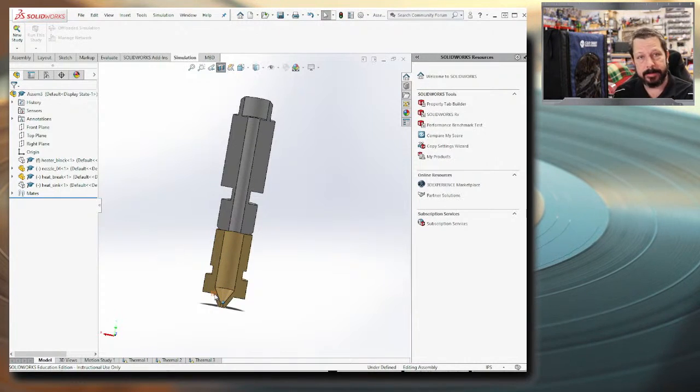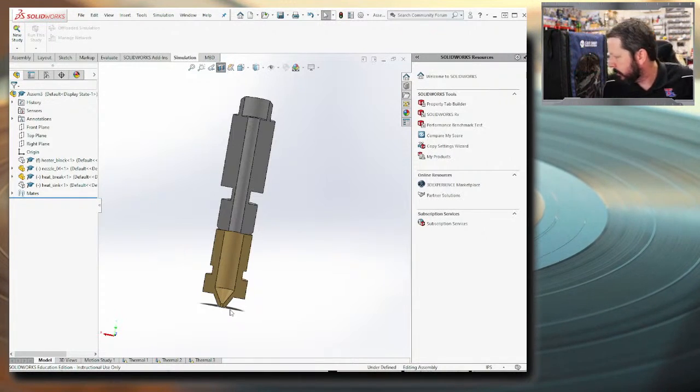Let's say you get a clog that you just can't get out of the Ender 3 style hot end. Take the nozzle off, shove the Bowden tube all the way through the thing, and it will purge everything out of there. At that point, you could even resurface the end of the Bowden tube. Let me show you what I use. Let's see. I'll have to find one.